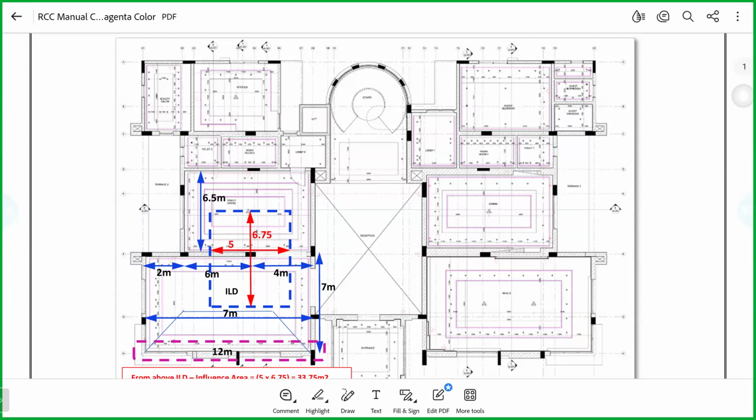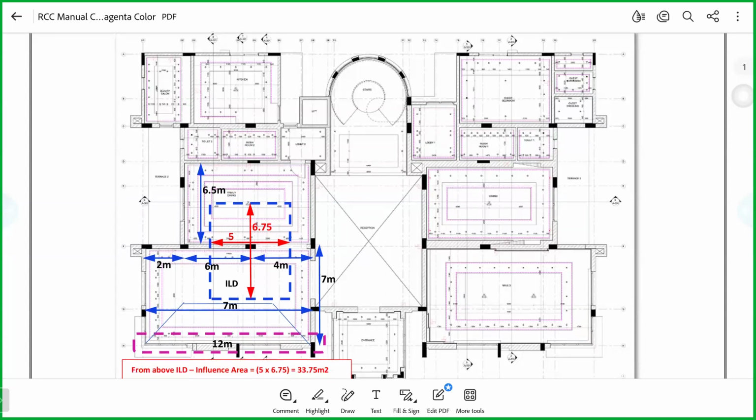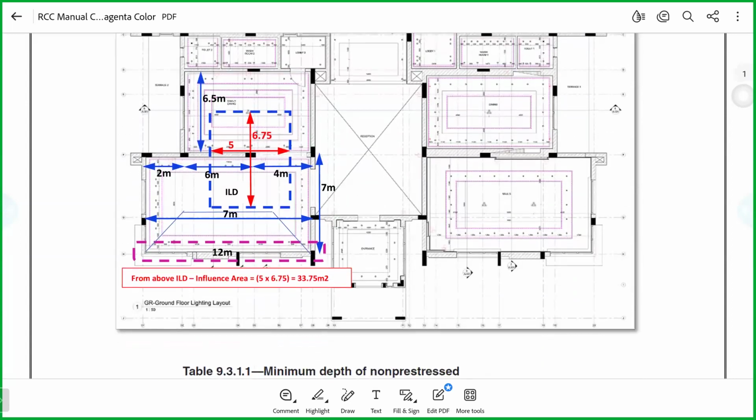Now the question is, what if we don't have beams? As I said, the second option for the frame structure is going directly with the flat slab option. In that case, the load goes from the slab directly to the columns, and directly to the foundation. There is only one element which we remove, the beams, which you may have or may not have. It's up to the designer's perspective. Okay. Now let's focus on the beam design here.